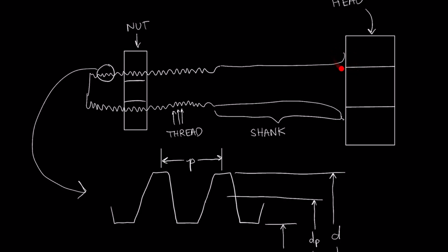We have this sharp turn, and I've drawn it with fillet radius, which is typical, but if you're designing a fastener from scratch and you forget to put in that fillet radius, you'll have a really high stress concentrator here. And then we have another stress concentrator basically at every single thread in the threaded portion of this bolt, right? We have lots of sharp corners.